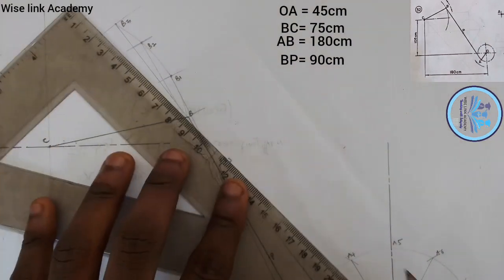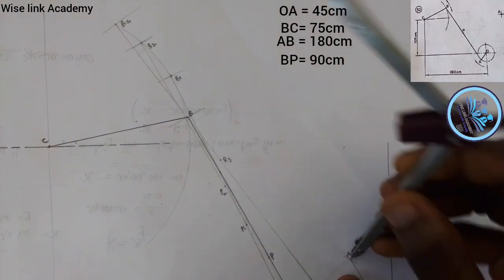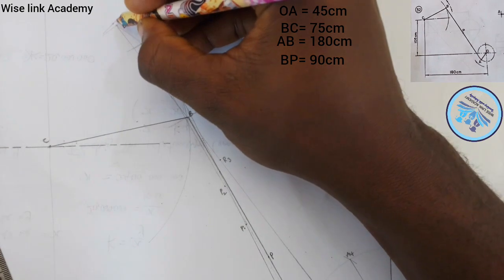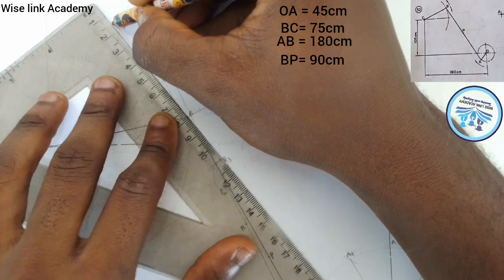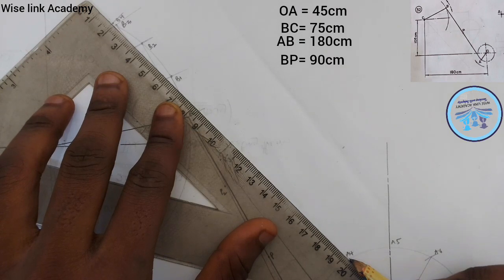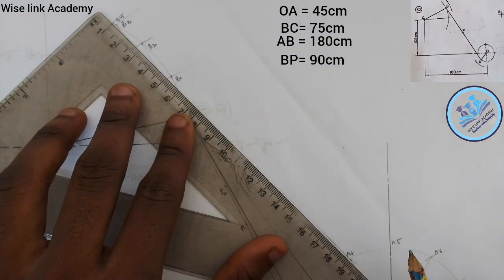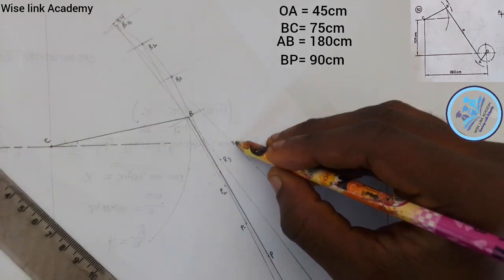Similarly, I will locate a point B4. So by putting my compass here and striking an arc again, that's how the arc is touching. So the arc is touching here. My B4. So connect B4 to A4 with a faint line this way, and measure out the same 90 again for somewhere here. So my P4.